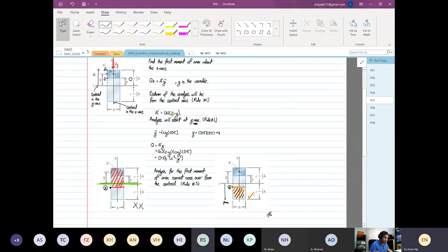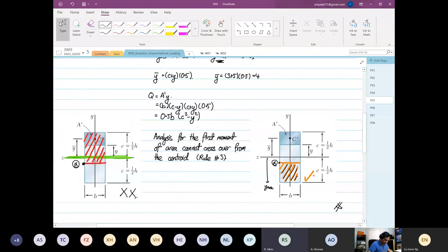Yep. So we're just splitting up this area because we're going to be interested in analyzing the shear stress at different points along there. That's correct. Right? Yep. So that's why your y is a variable. We are going to calculate the distribution. Likewise, we did our distribution calculation based on bending moment. Bending moment, we're also calculating the what? The distribution, right? Because stress is equal to My over I. Your y is a variable. Likewise, for this, we are looking for the distribution of the shear stress. Okay, good question. Anyone else?